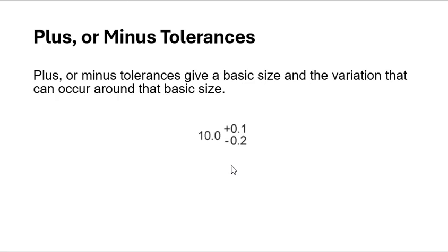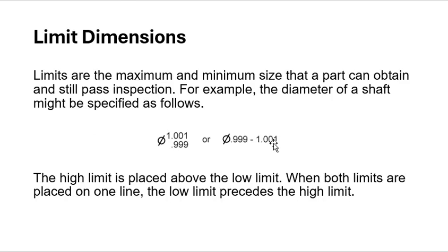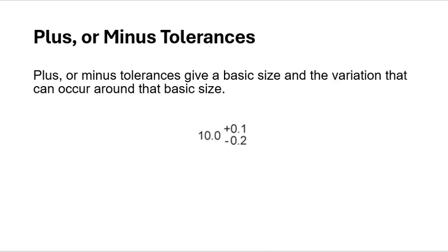The next one is your plus or minus tolerance. See, like how we write, very different. So I'm going to show you the very first one so you kind of see the differences. The very first one, for the limit, is a very particular way of writing, okay? No plus or minus. Now, we're using the plus or minus sign right there. See that? So here is your ideal value, and then we can go 0.1 up and 0.2 down.